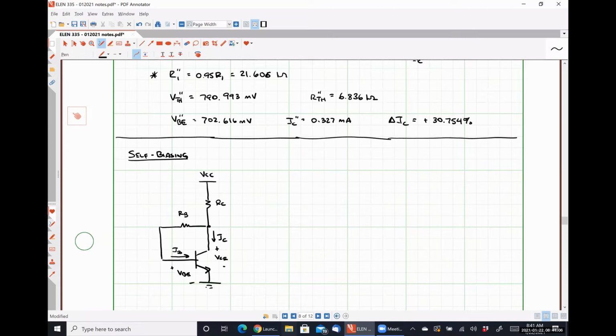So when VCE is less than VBE is when we enter into the saturation region. So we have VCE greater than VBE for all values of IC, other than, I guess, 0, right? So it's impossible to put this guy into saturation. So that's a pretty useful scheme, also very, very often used. We can develop our relationships for it pretty easily, right?